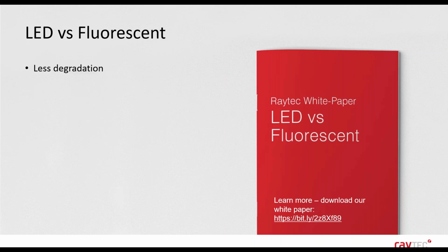of that study. The first one was that LEDs suffer from far less degradation than a fluorescent does. That means the luminaire will provide better output for a longer period of time. And because the rate of degradation of fluorescent in comparison to LEDs is much higher, the number of maintenance interventions are significantly reduced as well. So you're not having to retube the lamps as you would in a fluorescent, and that could result in big cost savings in terms of maintenance.